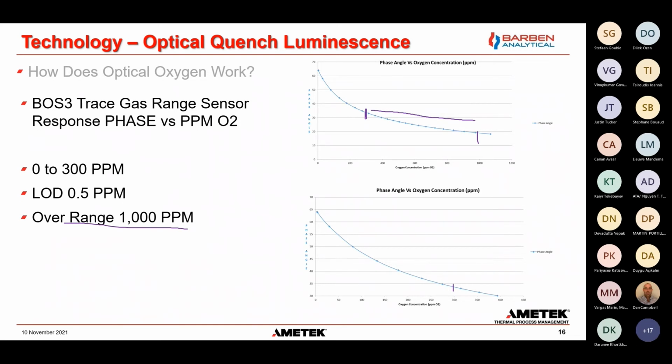And it makes sense for a lot of folks that are trying to measure zero again, or trying to measure a 0 to 10 parts per million system, that they want to look here. But then when they have a leak in the system, they want to see how high it goes, because they may be looking at a very large volume of gas. So the difference between 5 ppm and 200 ppm is a massive amount of air coming in from somewhere, if you're looking at a large gathering line or a gas plant or something of that nature. Okay.